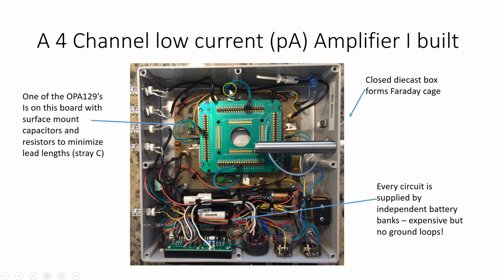And so unfortunately we are limited to quite a bit of stray capacitance, and that does limit our circuit performance. The whole thing's in a Faraday cage. There's a lid that screws onto this box, and I've scraped the paint off the regions where the screws go in, so the lid is well connected to the box, and when you put the lid on, all the noise goes away.